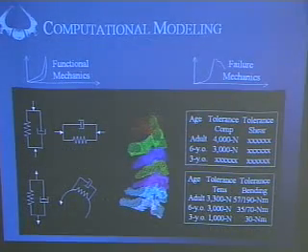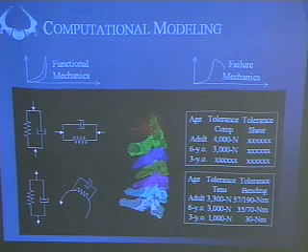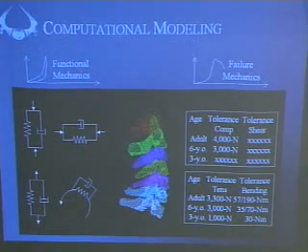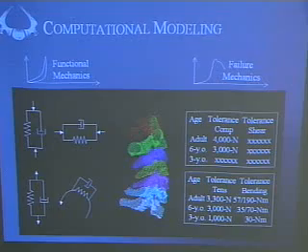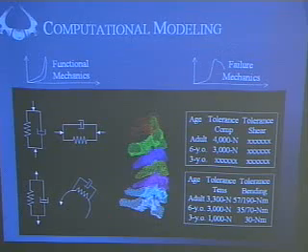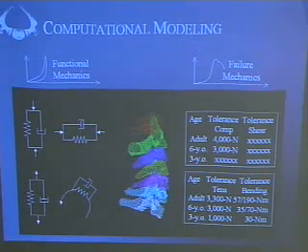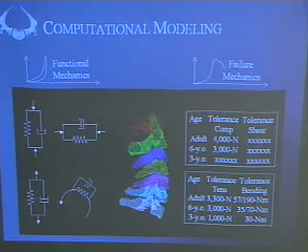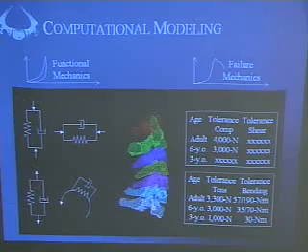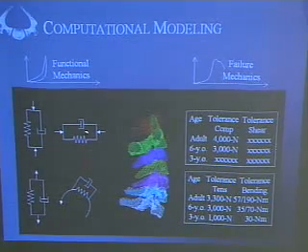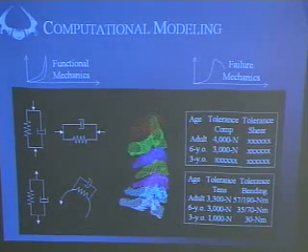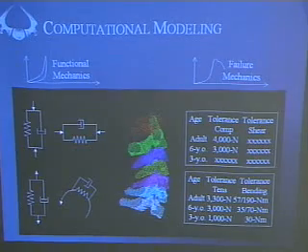Slicing this computational model a different way to give you another feel for the aspects that are involved in modeling the spine. There are two main criteria: the functional mechanics, which is the everyday functional mechanical response of the spine as you're walking around, and then there's the failure mechanics. When you take the spine to excessive levels of force or displacement, how do those tissues behave? As you can all move your head around, you can understand that there are compressive, tensile, bending, and shear elements that all need to be incorporated into this model to really get the mechanics of the head and neck motion appropriate for the spine.